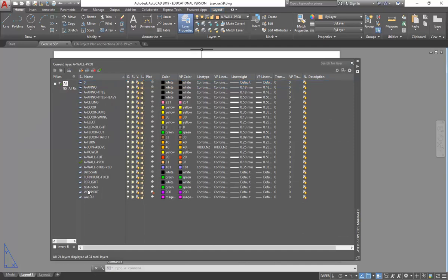Okay, so you'll see there I've got this layer that I've made called Viewport, and I've set that to be non-printing. You might have noticed, if you've made a dimension, that you'll also have this layer called Def Points, which is one of those system layers that AutoCAD makes for you, and it's always non-printing. So if you ever just want to have a layer that you can quickly choose to make things not print, if you've got Def Points, you can use that. But it's probably easier and clearer if you make your own layer, just call it Viewport, and then over here just make sure you click on that option there to turn the printing off.